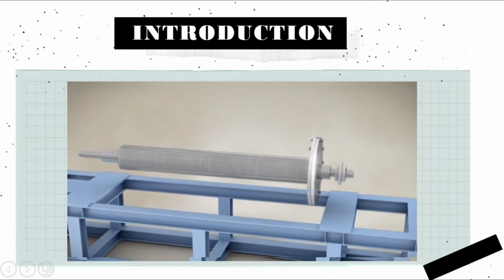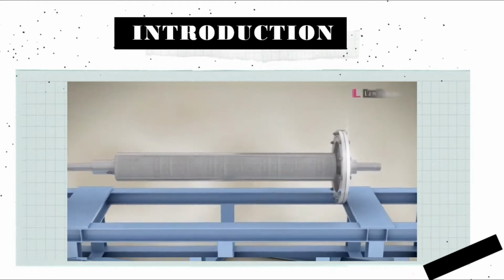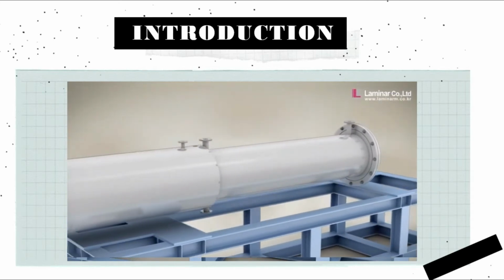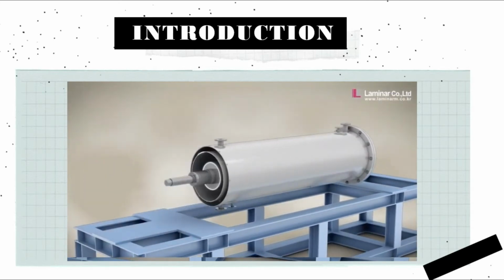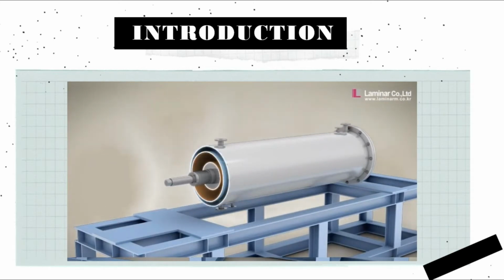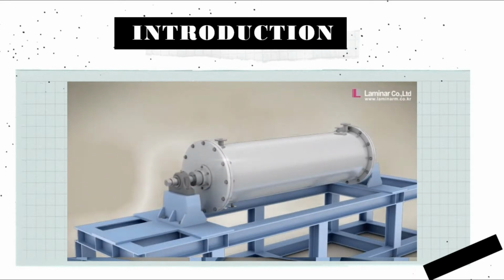A plug flow reactor consists of a long, straight pipe in which the reactive fluid transits at steady state, having no accumulation. The main assumptions of this model are that the fluid is completely mixed in any cross-section at any point, but it experiences no axial mixing. Contiguous cross-sections cannot exchange mass with each other.